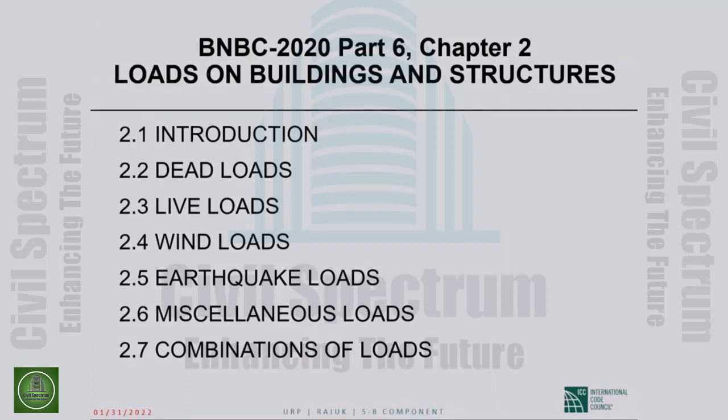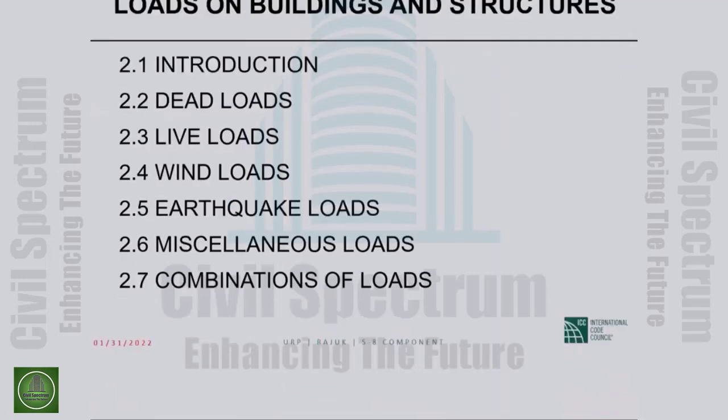You design your structure for combinations of loads, not for just one load. And I will take you through section 2.7, load combinations, before I get into the loads themselves. I think it's better that way. You see what you do with the loads in design.